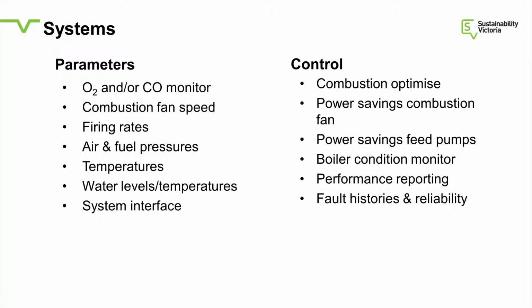If the boiler's sitting at low fire for a lot of the time, or low load, the combustion fan uses much less energy than if it has a damper setting. So that's quite something people don't pick up often, but you find that sometimes the savings in the fan's almost as much as the saving you achieve on the gas. So it's certainly worth considering in any evaluation you do.